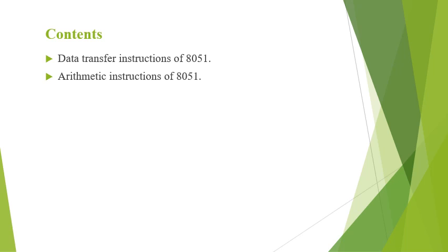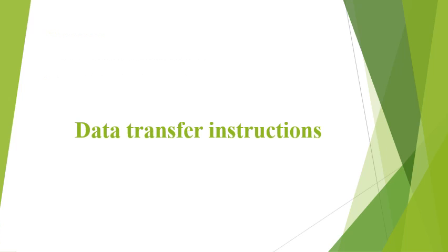In this video, we'll study the data transfer instructions and arithmetic instructions of 8051. So first we'll see the data transfer instructions in 8051. The first instruction we have is MOV destination byte, source byte. So the instruction has two operands.